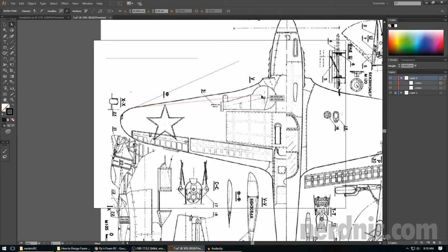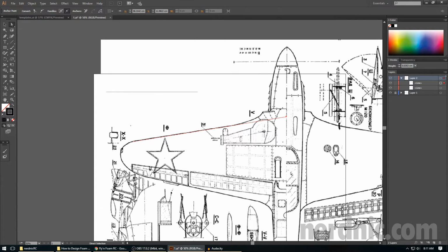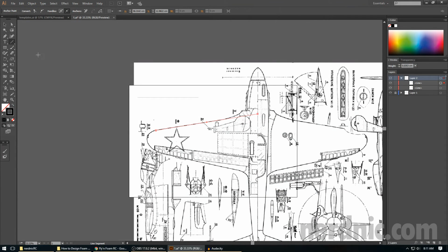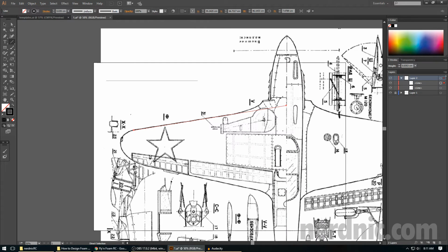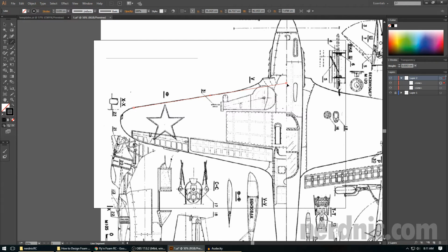Now what I'm going to do is extend this past this curve right to the center of the plane. Now if you're drawing, or your 3D doesn't have this line in the middle of the plane, I would recommend going and adding it. You should probably grab the center, make a line just so you have that point, and this just helps with the alignment later. In this case I have one, so I'm going to undo that, and I'm not going to worry about it. Okay, so I've got it to about the center here. I'm on the leading edge, I like that.